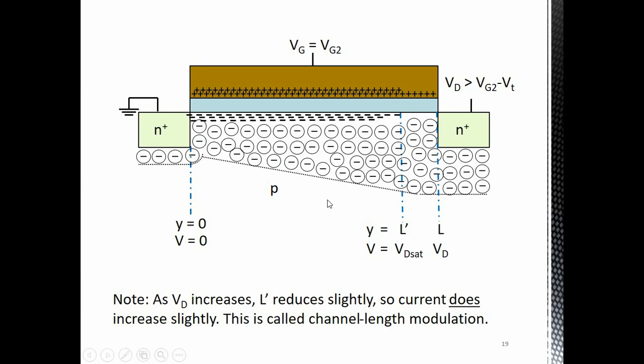Alright, as I said, this is complicated two-dimensional, but this is a P region, so a PN junction. There are electrons available on the P side of the PN junction, and because there are electrons available, current does flow across this reverse bias PN junction. And so these electrons will be swept across at high velocity across this pinched off region and contribute to current.